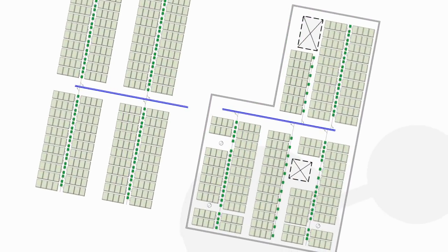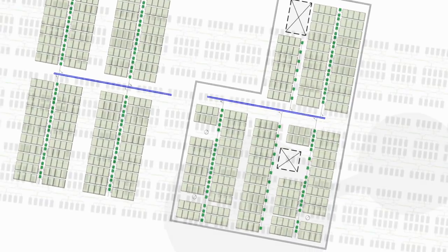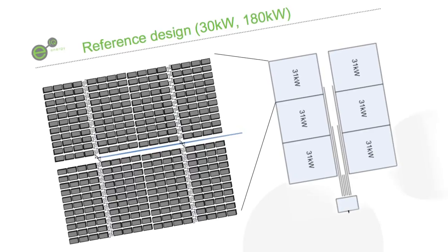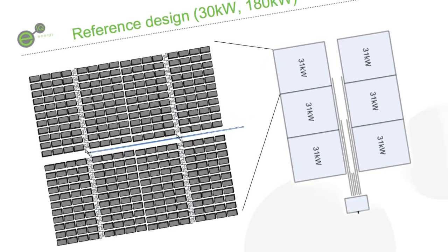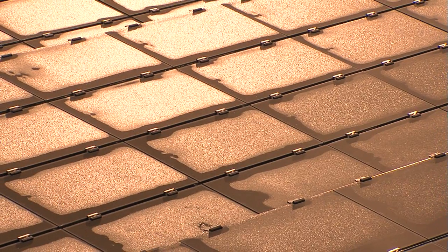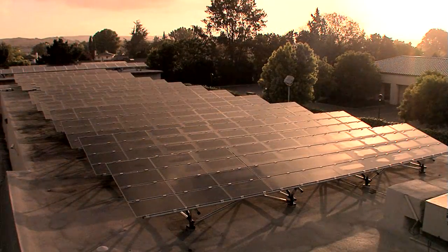Designers gain flexibility regarding PV panel location, orientation, and overall system size. Installers have a safe, simple wiring plan, requiring less wire and terminations. And most importantly, system operators improve their expected output and payback. The vBoost will improve the energy harvest by 5 to 30% by performing MPPT at the panel level.